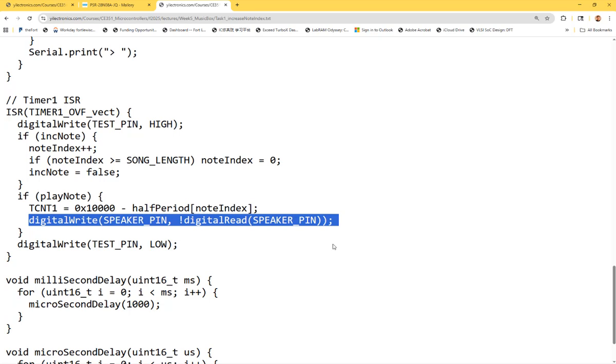So the ISR and the timer are controlling which time period? Very simple question. Which time period is the ISR controlling? Half period, right? Because every time the timer's up, it toggles once. So when timer's up, toggle it, timer's up, toggle it, timer's up, toggle it. Make sense? So we're using ISR to toggle that pin.